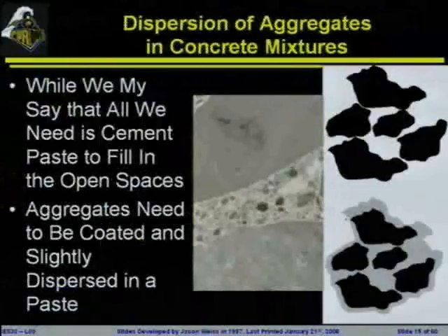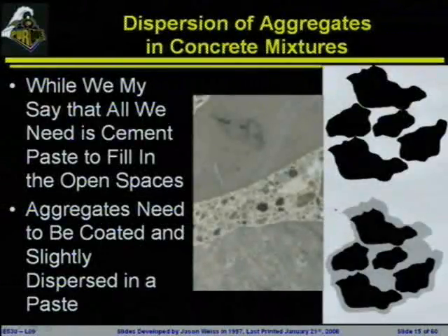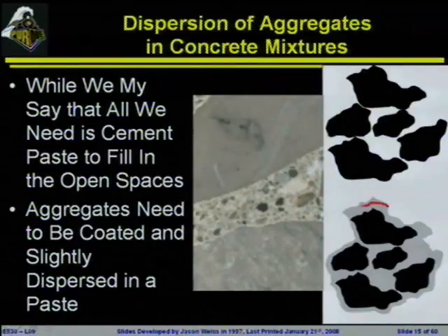What we are really just after is having enough paste in the system to glue the rocks together. So the overall idea is we want to have a thin coating around the aggregates that allows these rocks to be glued together. That's really what we're after. That's really the key issue.